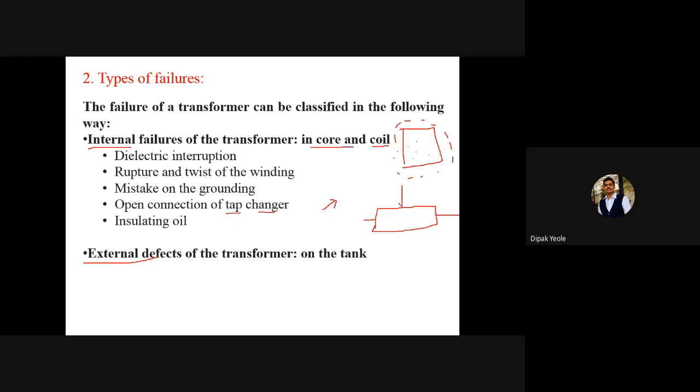On the rheostat, there is one point available, and you are going to change this point according to your resistance requirement. Let's say this is the maximum value of the resistance, and this is the minimum value of the resistance. So if you want to minimize the current, you have to put this tap to this side. So your resistance is maximum and current is going to minimum. Same way, if we are interested to make the resistance minimum, so that the current is maximum, then we have to put the position like this.